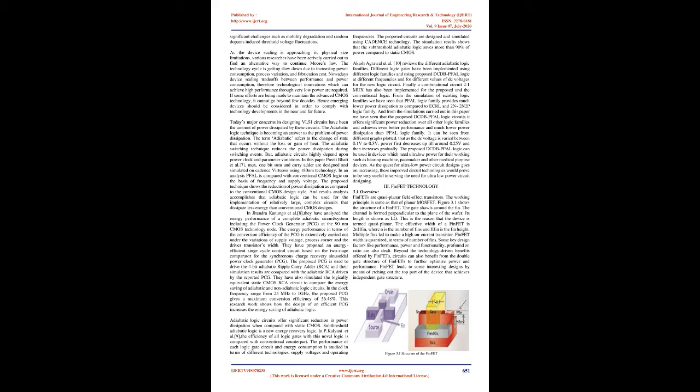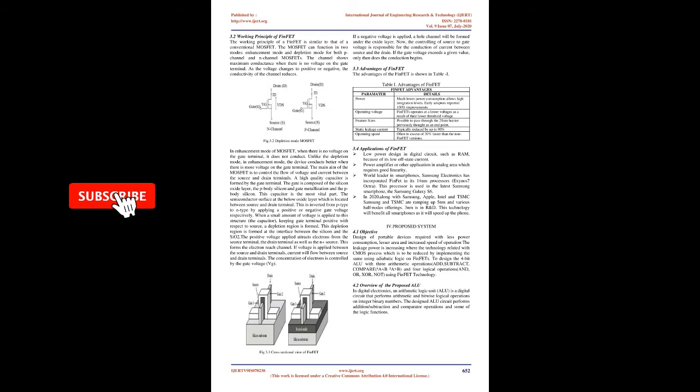Shivani Chopra et al. [6] provide an overview of the issues faced by the downscaling of MOS devices. For retaining growth in device density, the scaling issues like the power supply and threshold voltage scaling, hot carrier degradation, gate oxide tunneling, random doping fluctuation, high electric field, parasitic resistance and capacitance, source-to-drain tunneling, and short channel effect should be well understood. A possible way for the microelectronics industry to keep up the high-density pace is to shift from the traditional MOSFET-based standards to one based on nanostructures at the molecular level.